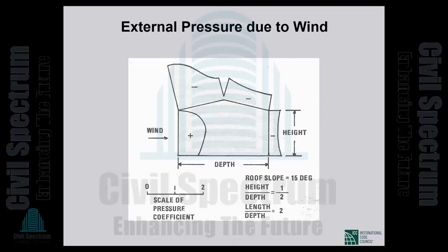And that is a very typical failure mode in a windstorm. If you go after a hurricane to look, this is what has happened to many of the buildings. So the first challenge we have in wind design is to tie the roof down to the structure. There are hurricane straps and things to securely attach the roof to the structure. And once you have done that, the structure has to be attached to the foundation.